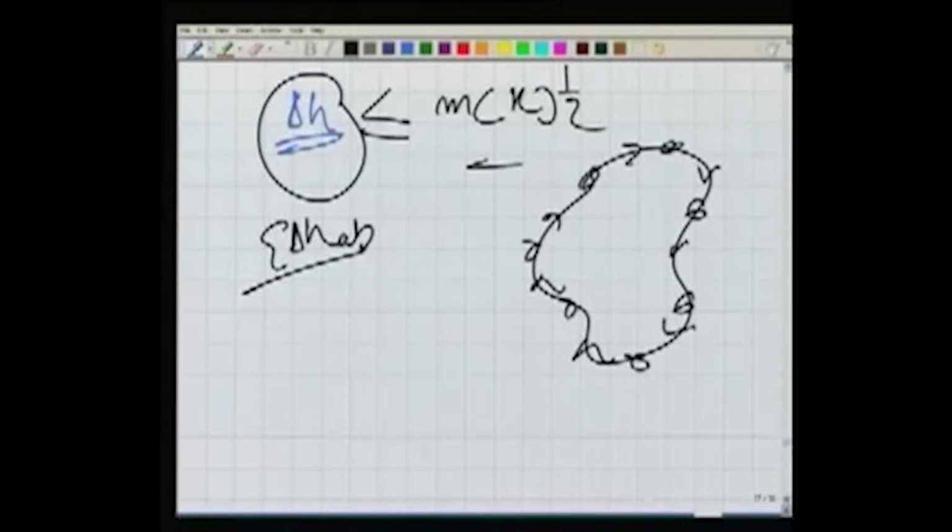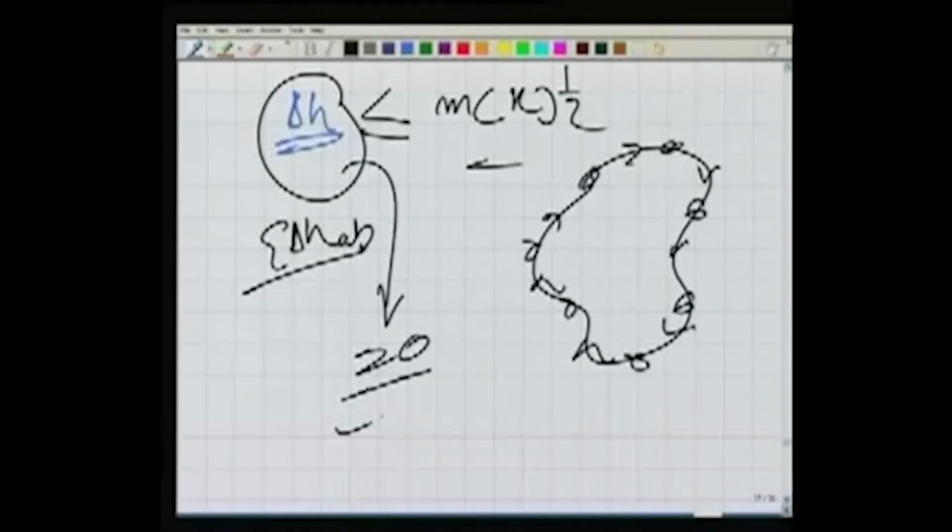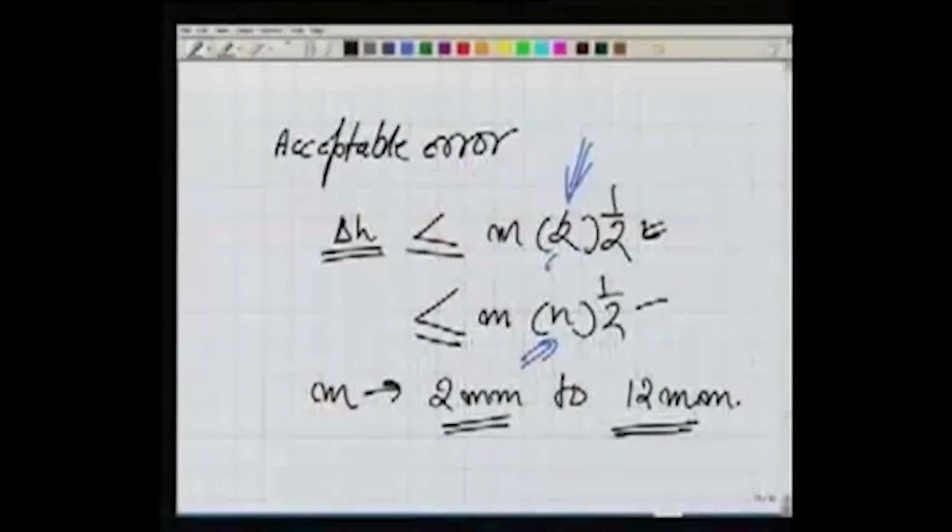So what should we do? We should try to adjust our observations. We should apply corrections to our observations in such a way that this becomes 0. Now how do we do it? There is a simple method. As we are distributing the errors, or rather we are finding the acceptable error, proportional to the distance in kilometer or proportional to the number of settings, similarly we will try to eliminate the error also, or to apply the corrections.